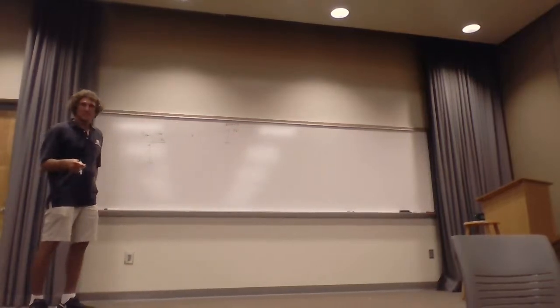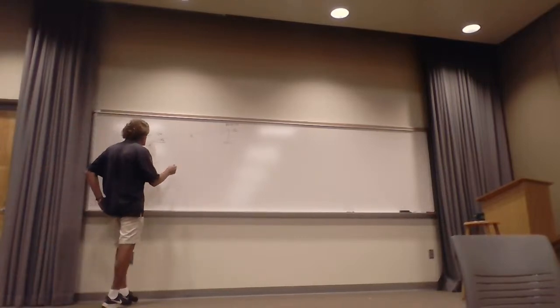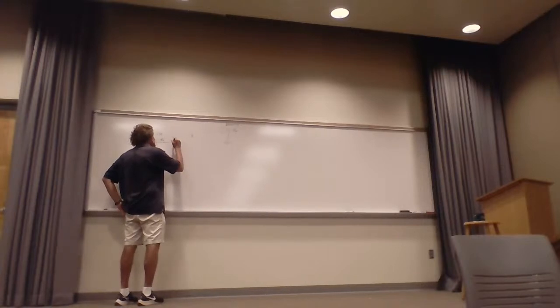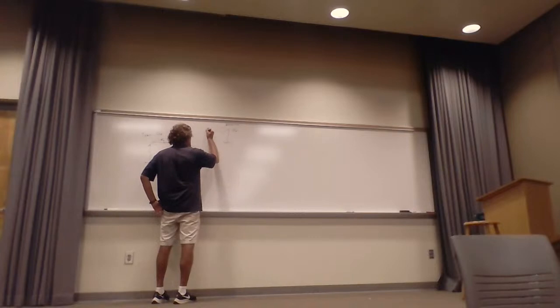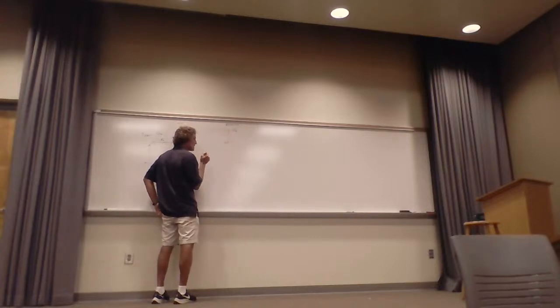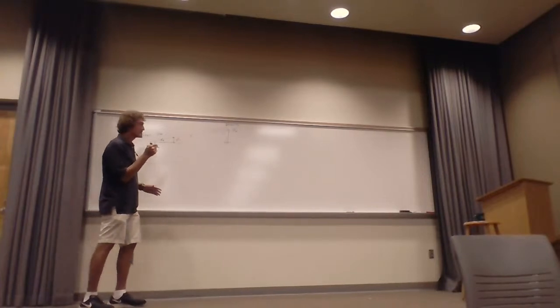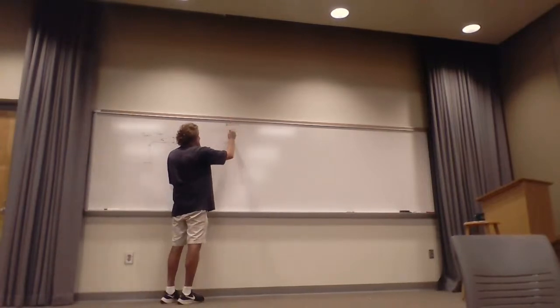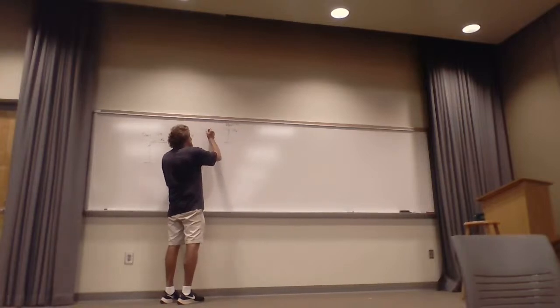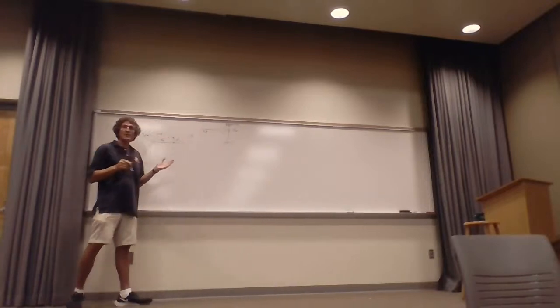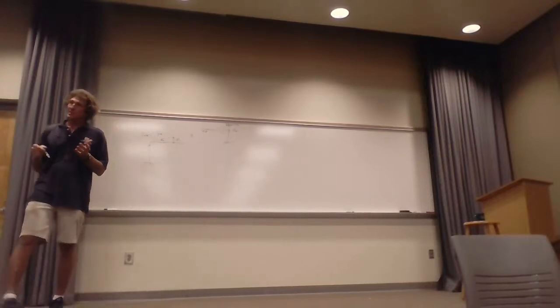It's a quick question. If you're given one angle, like if they're not set up for maximum power, is there a way to calculate the angle for the other one, or does that have to be given? Well, you have to know something about the geometry. If this antenna is vertically upright, and the gain is with respect to an off angle, you might as well call that alpha. Then yes, if you give enough information, you can deduce it.